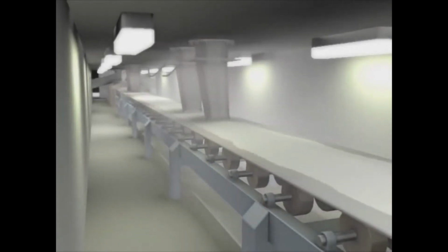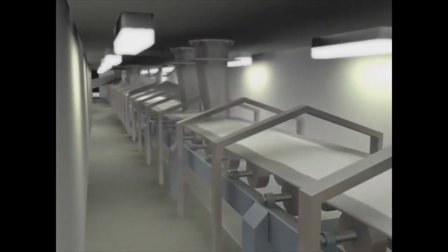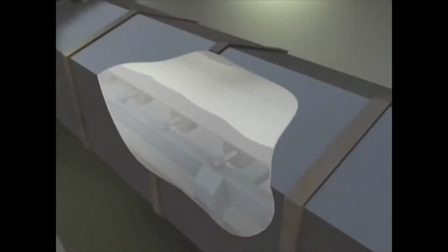However, in 2007, the company enclosed the conveyor belt with stainless steel panels to protect the sugar from possible contamination. The enclosure was not equipped with a dust collection system. As a consequence, sugar dust would now be trapped inside this enclosure. On February 7, 2008, clumps of sugar were found blocking one of the discharge chutes.